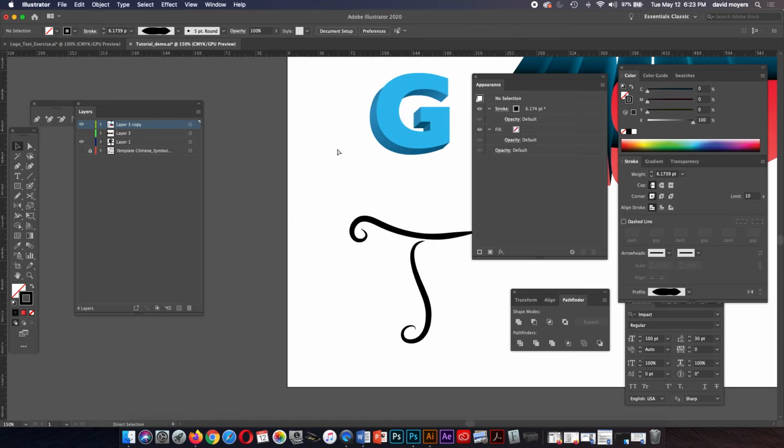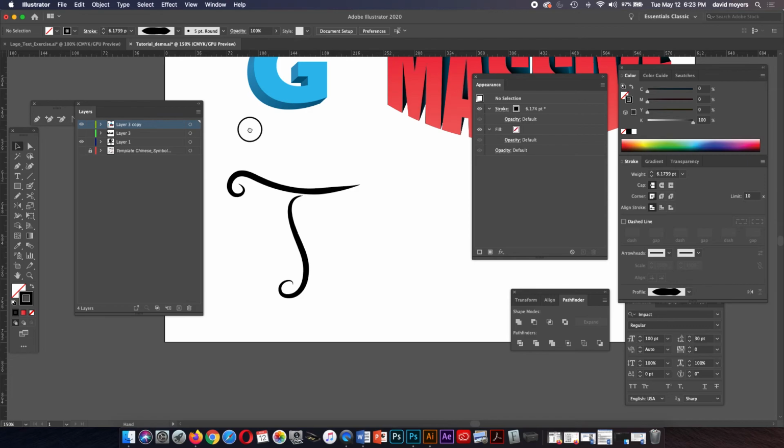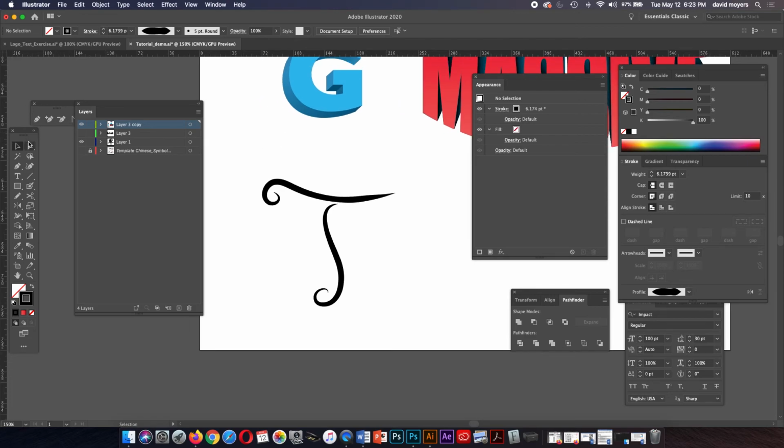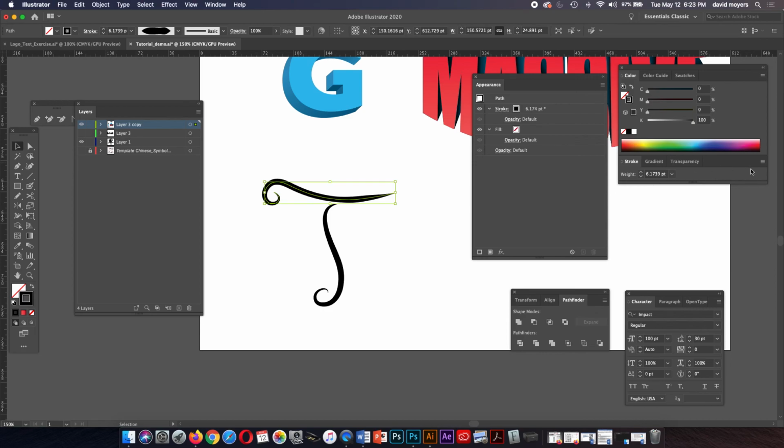By the way, this was happening to me when I was working on a project. I changed the width on a lot of strokes, and I said, yeah, I might not want that. If you ever want to turn this off and start over again, you can click on your stroke, and up in here on your control palette, you will see this. You can also see it under the profile of your stroke. Now let me show you. Let's hide the options here. So you may not be seeing it on your stroke. Let's go show options here.